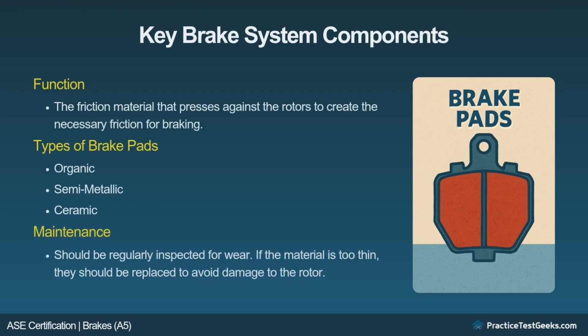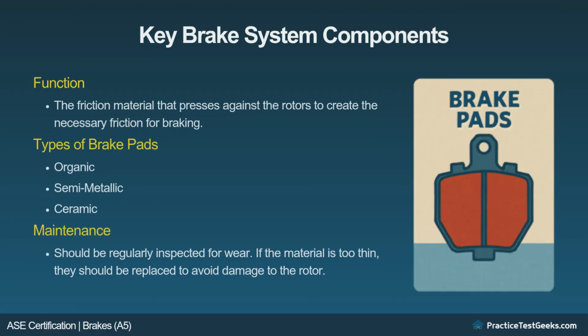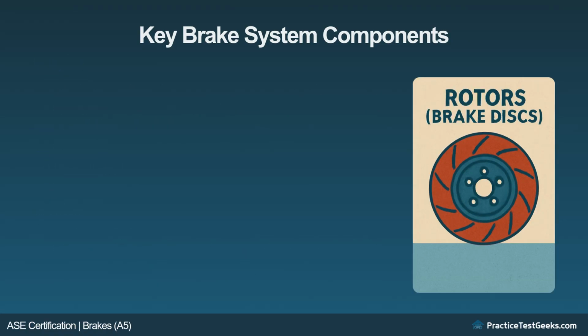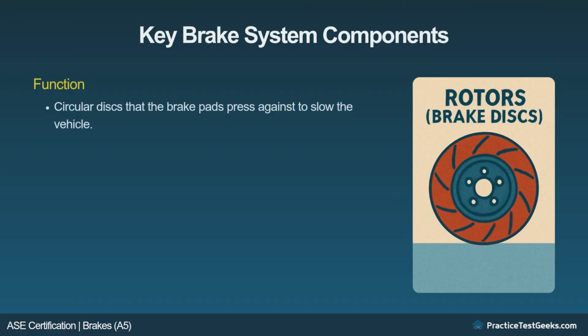Brake pads should be regularly inspected for wear. If the material is too thin, they should be replaced to avoid damage to the rotor. Rotors or brake discs. Function. The rotors are the circular discs that the brake pads press against to slow the vehicle.